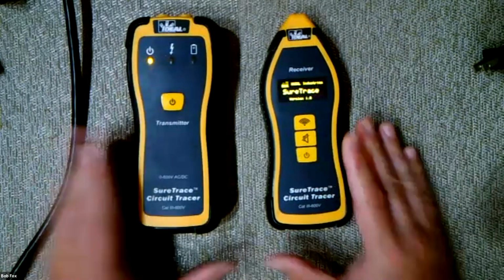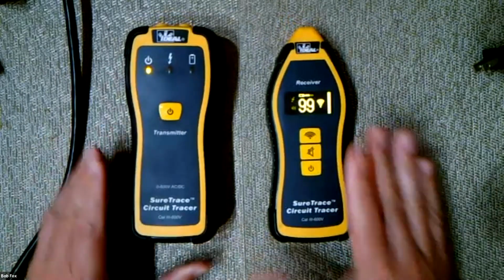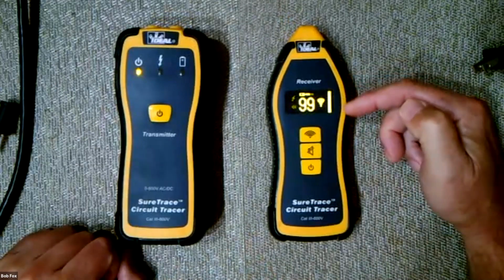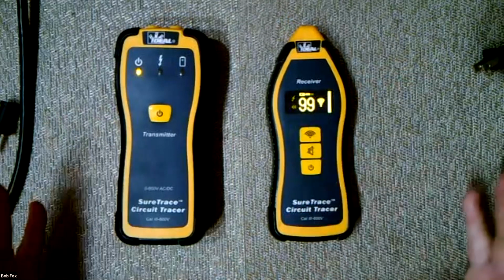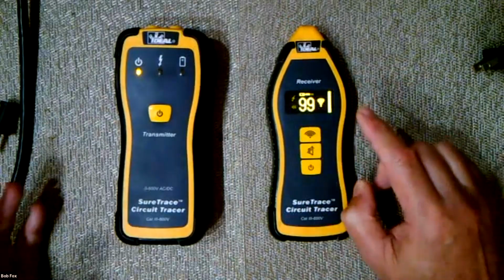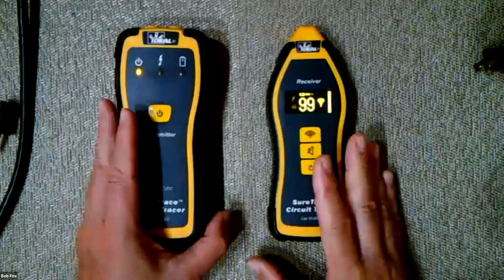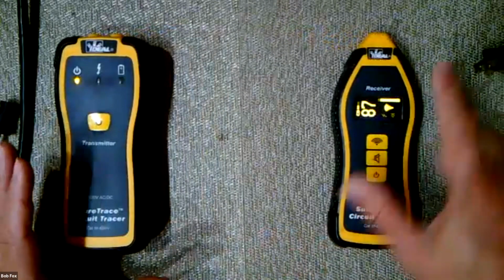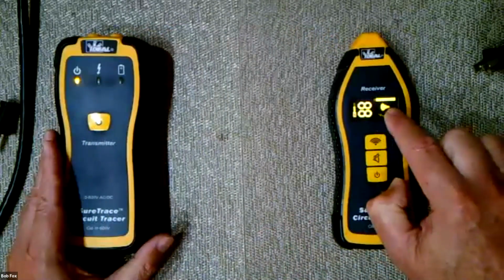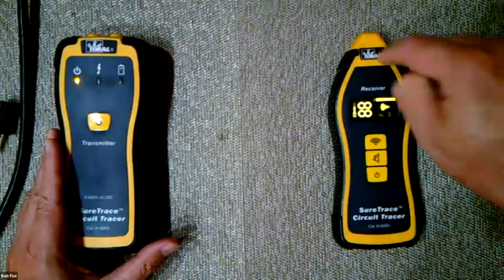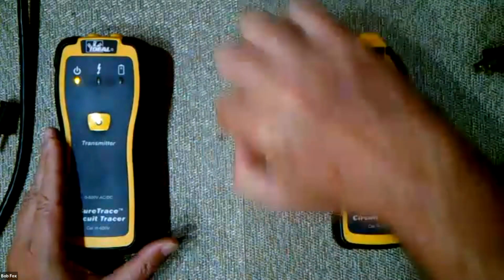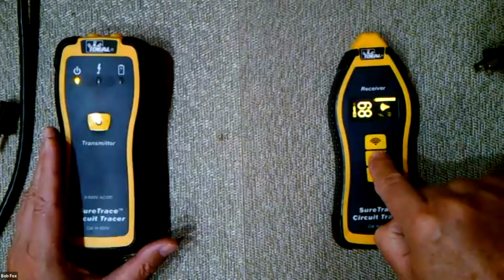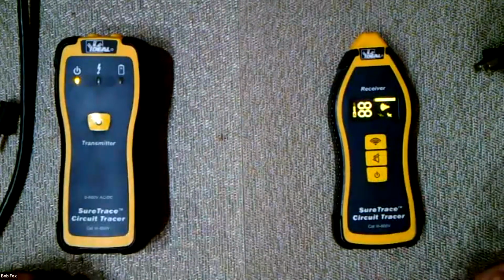And then here's the receiver. Obviously it's audible and it's analog. You can see the analog scale, but it's also digital. So instead of having just 5 or maybe 10 LEDs, it's got a 0 to 99 scale. That makes it very, very sensitive. I'm going to move these apart, and as you can see, as it twists a little bit, the display rotates in 90-degree increments. So as you're undulating up and down a wall or what have you, you're going to see... I'm going to shut that sound off just for a second. There obviously is a mute button on there.